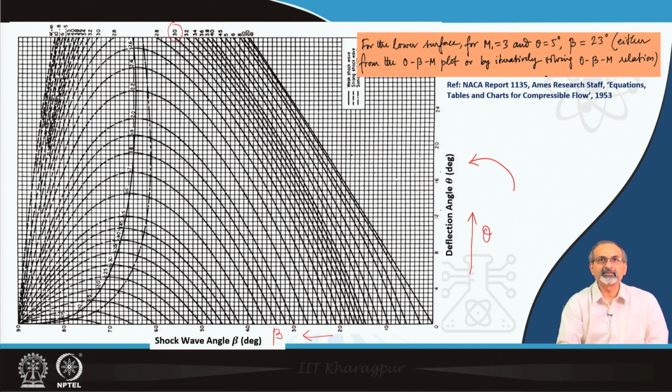So, for example, this is the one that we need for our purpose, and accordingly you have to read the value corresponding to the compression angle. You have a compression of 4 degrees here, and between 4 and 8 you have 8 divisions, and therefore the 5° angle basically comes here.